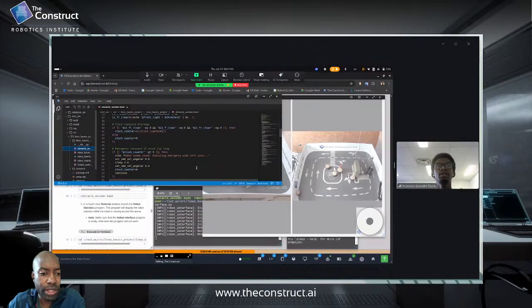Okay, so within the emergency recovery, I see that you're setting angular velocity to 0.6, right? So that's like a 60-degree turn, actually. Yes, I'm doing 360 divided by 6. And you're hoping that after making that turn, the robot will be clear of whatever.